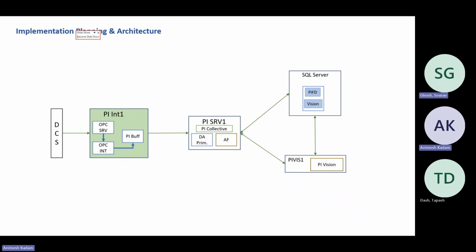When it comes to Pi ProcessBook, I understood that it is a tool sitting on my machine. When I configure it, that configuration is sitting, I don't know where, but for me it's sitting on my same local machine if I'm saving it. And when I open it and refresh it, it goes to my Pi server, fetches the data, and then updates the data.